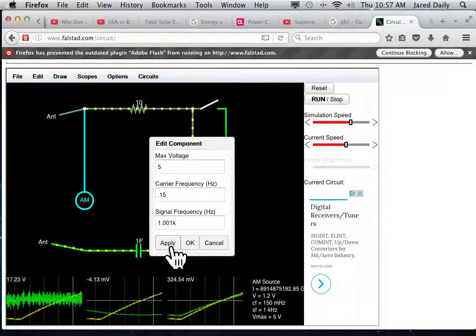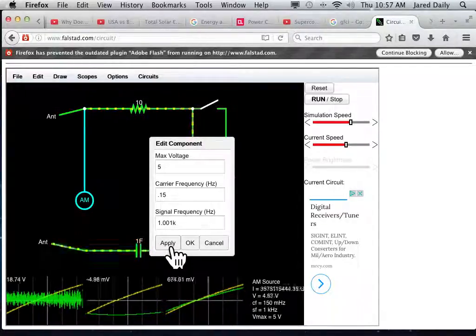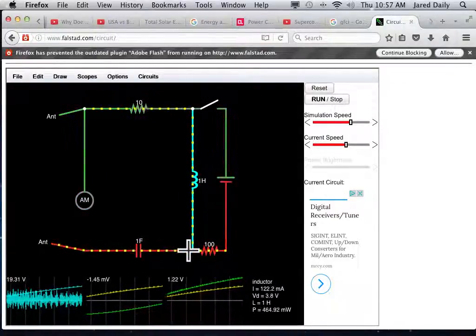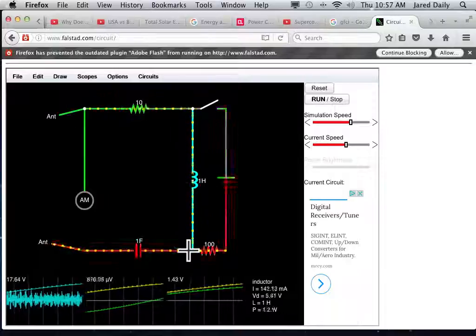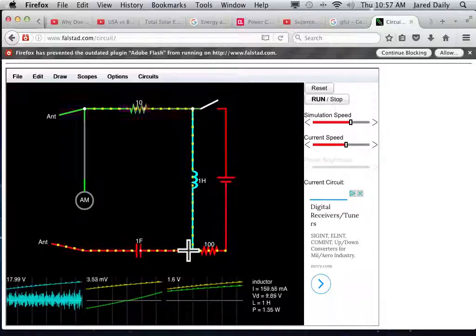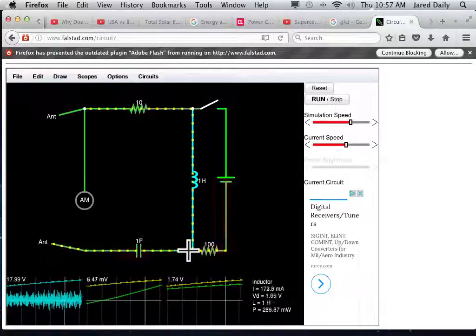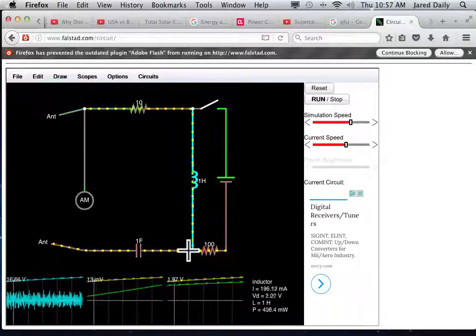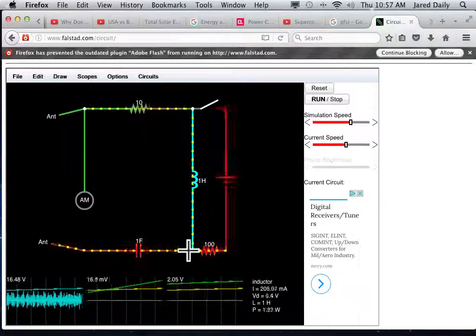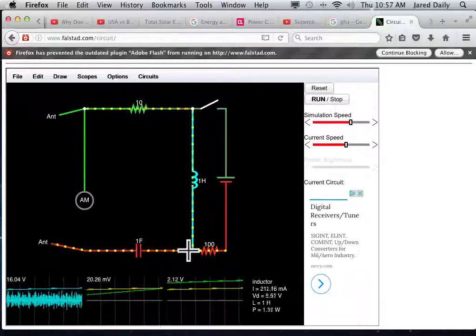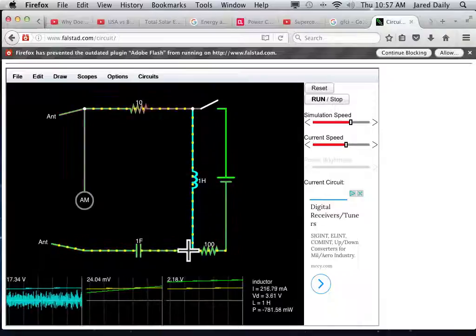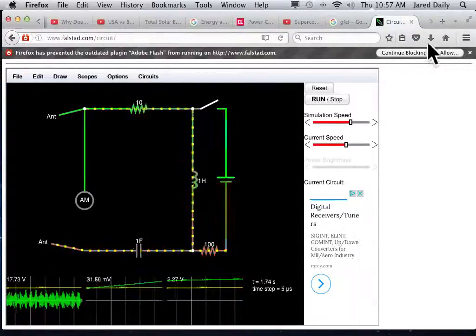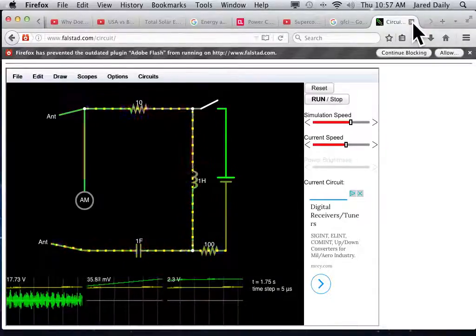And now we're seeing a huge rise in current, right? Which is what we should get. So now that we've matched up our frequency, that's when we'll be able to hear. Once the frequency is correct, you get this huge current flowing, and that huge current can drive a speaker, so that you can hear something. Right? So that's kind of the idea there. That's definitely the idea of the resonant frequency.